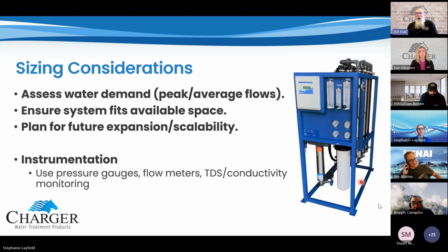If you're operating on surface water, for instance, in North Texas, all our water comes from Lake Ray Hubbard over here. Surface water has got a lot of organics in it. It's got a lot of suspended solids in it. It's got a lot of other things in it. So therefore, your flux rate is how you measure how much water that membrane should be producing. It's measured in GFD, gallons per square foot of membrane surface per day.